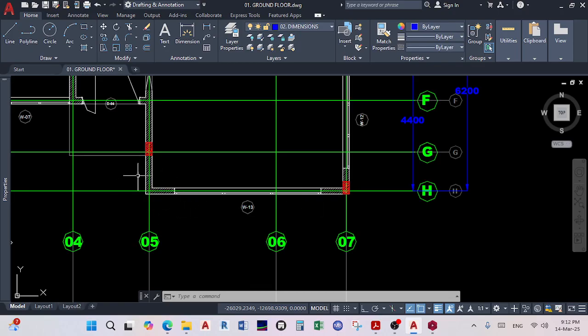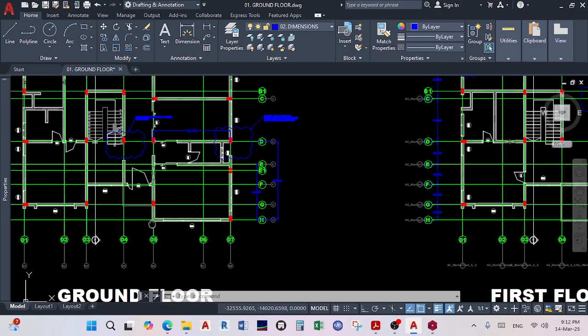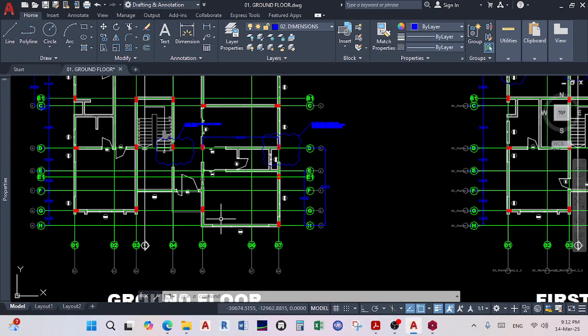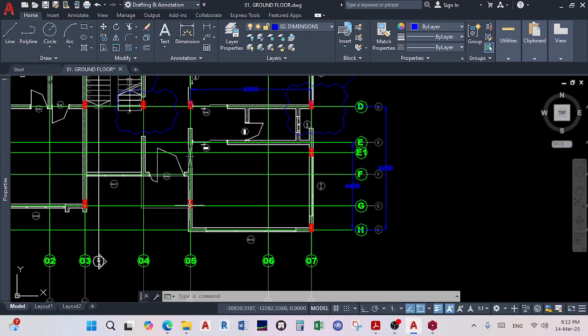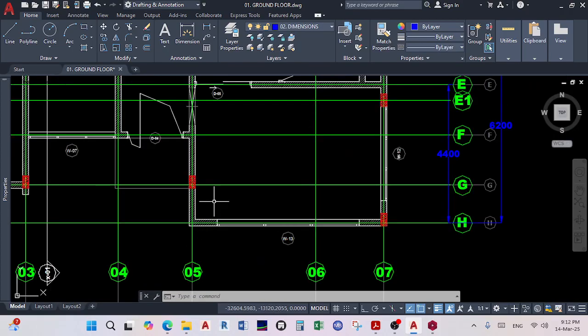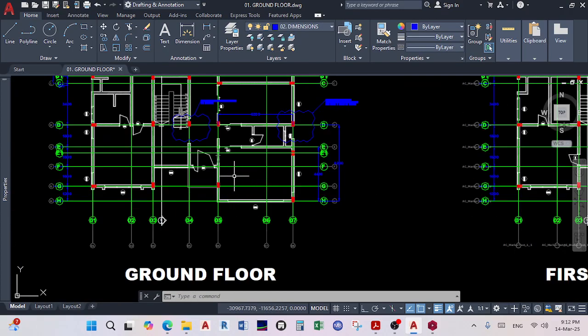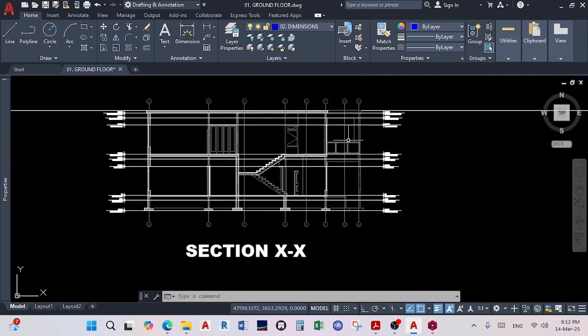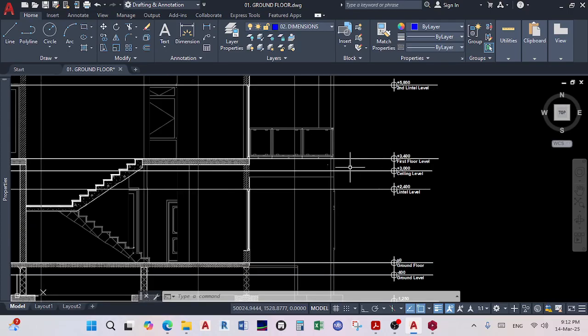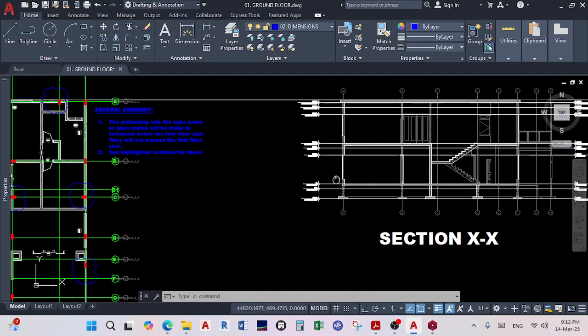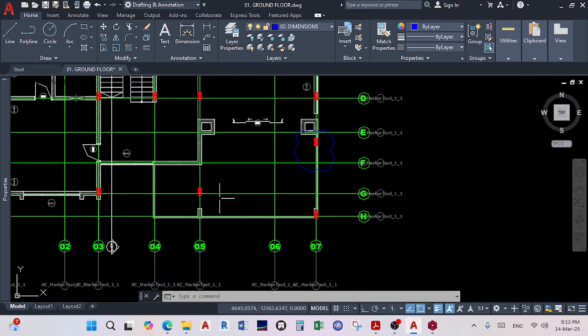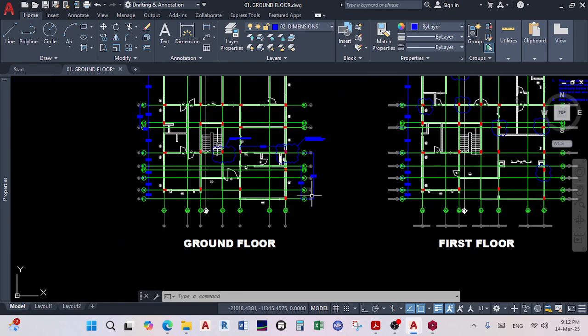So I added a column here and one here, meaning the only point where I'll have something like a cantilever will be in this section here at number 5H, because from there to there I'll have a beam, then this one will just be suspended, and then from there to there I'll have beams. And also, why I'm so confident in this is this will be a balcony area, right? So you do not expect, except if you lived in China and you used to have parties at the balcony, then now that's an issue. But anyway, we'll run the analysis and then we'll see.